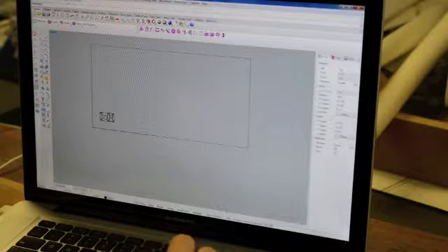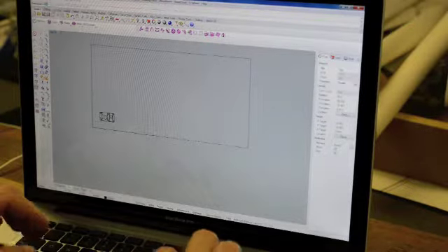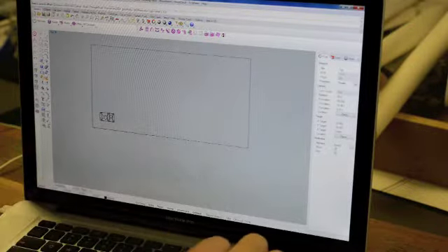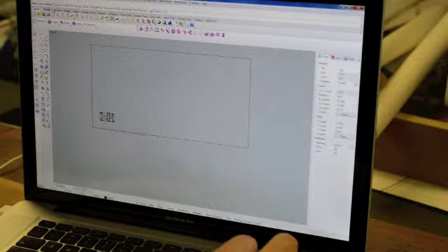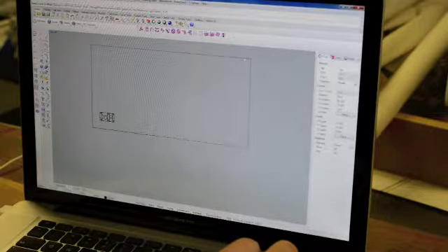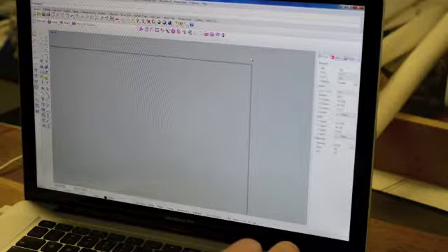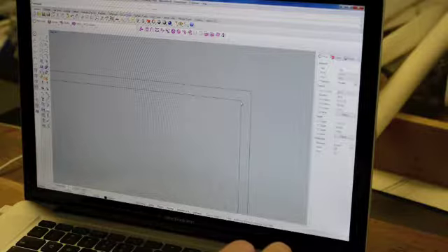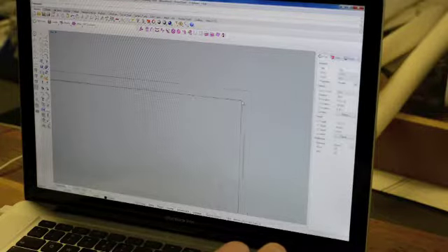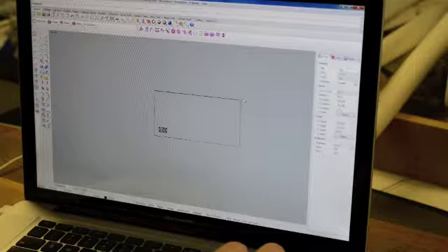And then we're going to offset 1.5 inches because that's what we did downstairs with that operation. So this is where we're going to actually put our stock. If you have the bed 1.5 inches off on both sides, that helps us align things perfectly.